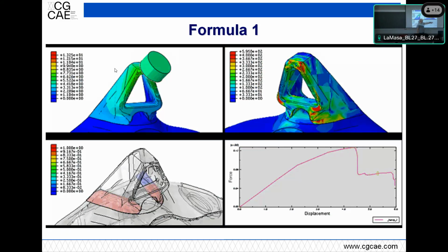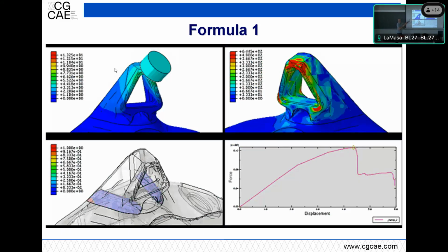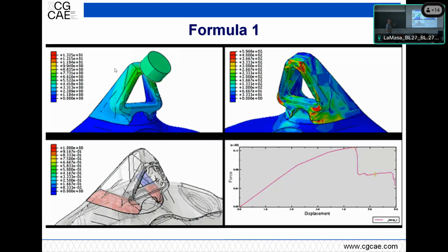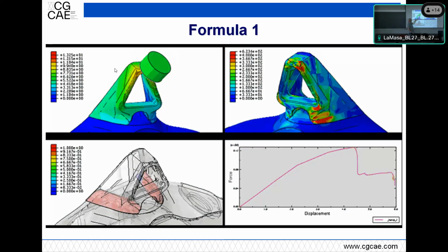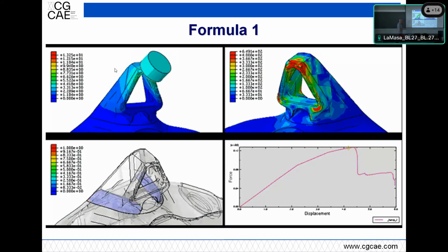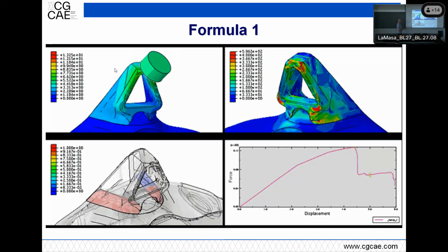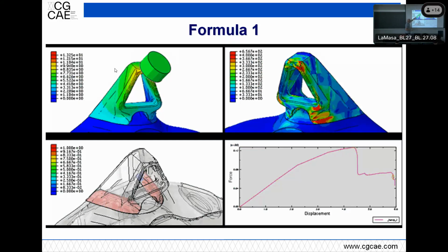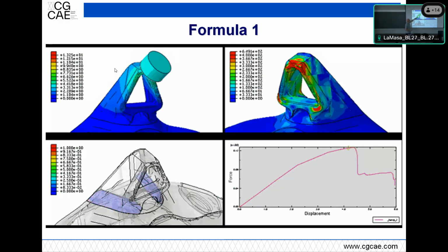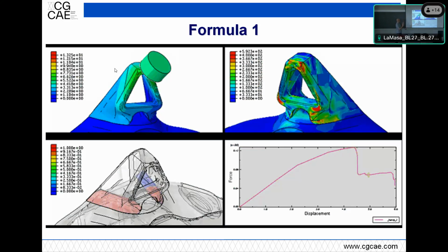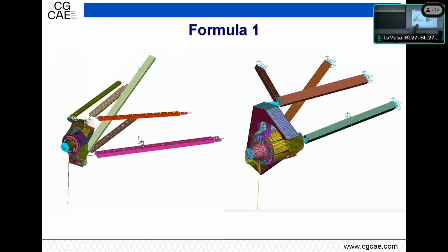And you see here the graph, you have different steps. So the loads come to a certain point. This was at the very beginning of the design. So it was the first steps, done with this strange shape, a very sharp triangular shape, which was wanted by the aerodynamics. Then the philosophy changed, still made with rapid prototyping, but with some sheet metal approach, as if it was a boxed structure. And it was what was on the car.